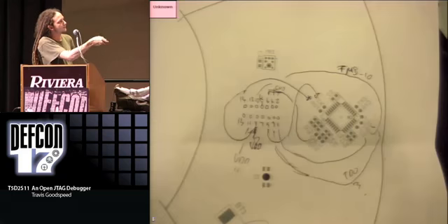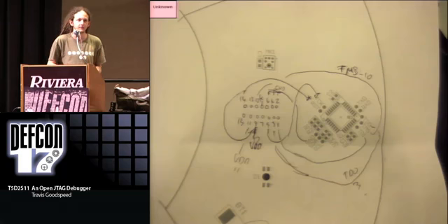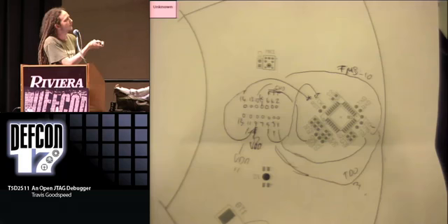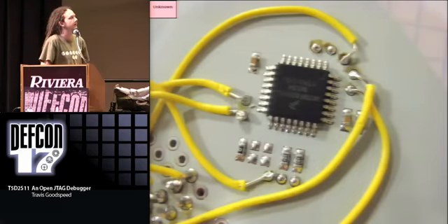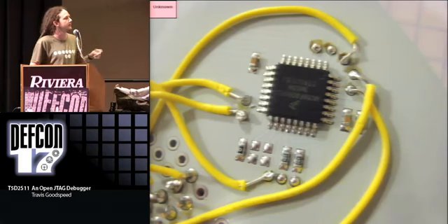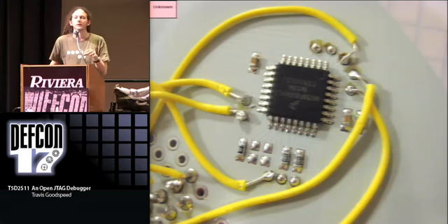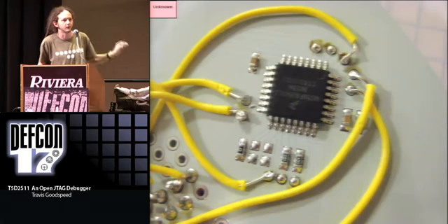Those are wired up. This is a diagram that someone lent me in the hardware hacking village. I'm not sure where he got it, but probably from your CD. And if you wire all of the pins up correctly, you can then speak to your badge externally. And unlike the bootloader, which connects to the serial pins, I think it's those two there, unlike the bootloader, this never goes away. So even though you might be able to damage the bootloader of your chip through software, there's nothing that you can do to hose JTAG.